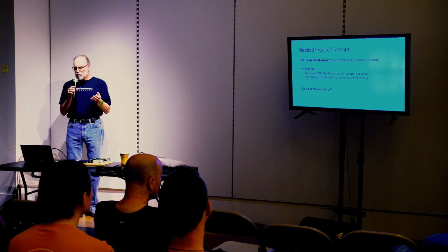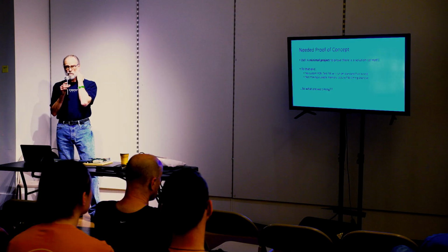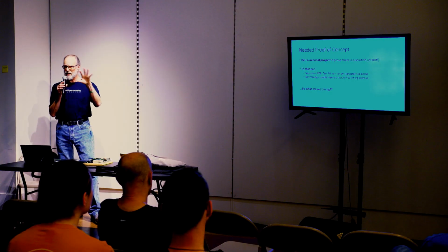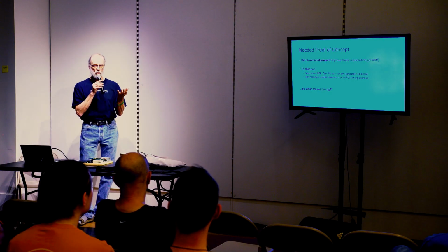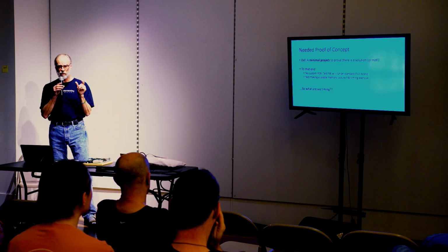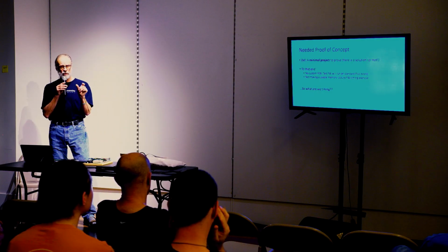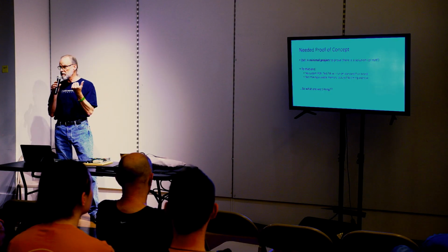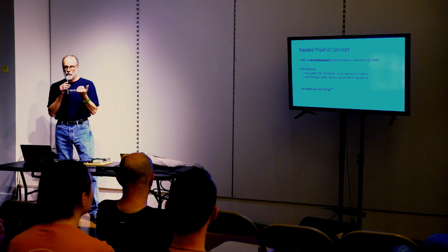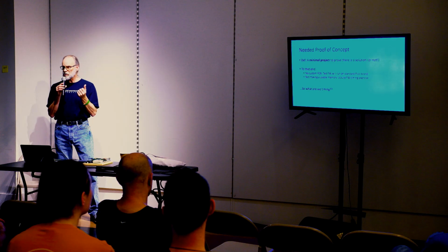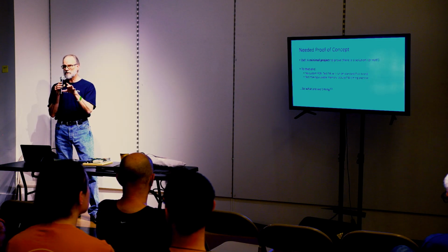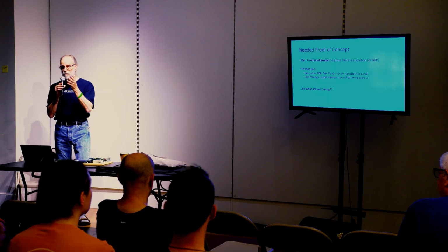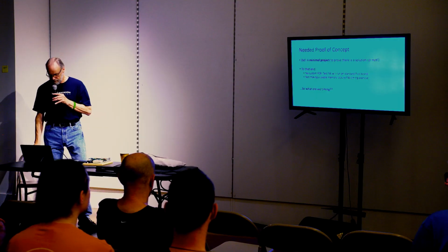So for that, I needed a proof of concept. And if you haven't done one of those before, this is a prime example of why you would want to do one. I did not want to redesign that whole board just to test and find out that it wasn't going to work. So I wanted to do a minimal project that proved that I could actually do what I needed to do. So to that end, no custom circuit board. This thing was just going to run on a standard Pico board. And I wasn't actually trying to make a usable memory. I'm not going to connect it to anything. I'm just going to hook it up to an oscilloscope and a timing generator and make sure that it is responding at the right times that it needs to.